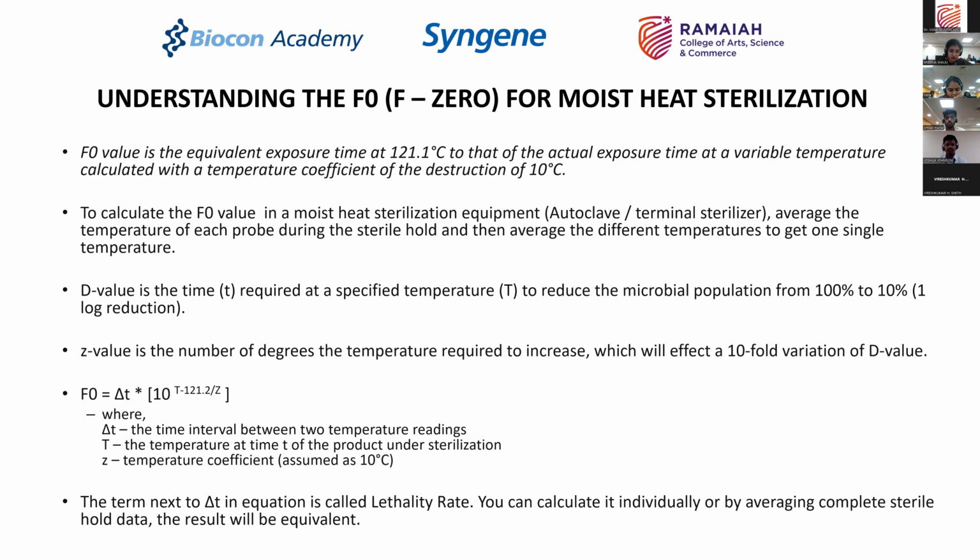So when you are trying to get into a calculation of an F0 online, I remember I told you that in the autoclave cycle, I will program in the software that the F0 value should get calculated automatically by the program. What is the program doing? The program is measuring the actual temperature T. The delta T is being measured because it is calculating that F0 value between a specified time interval. So I can say calculate the F0 value every 5 minutes.